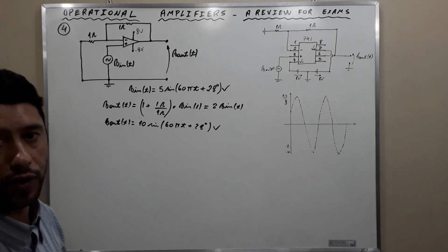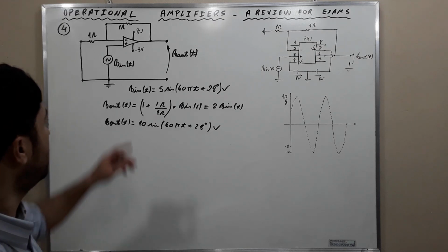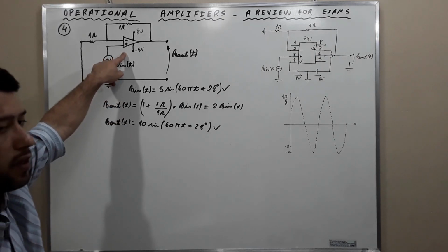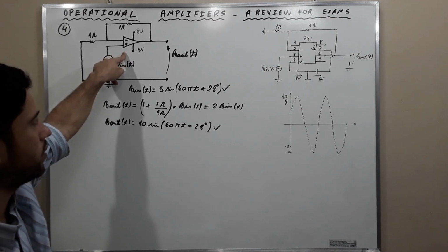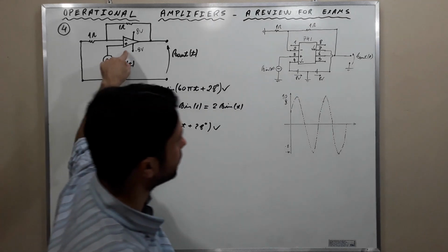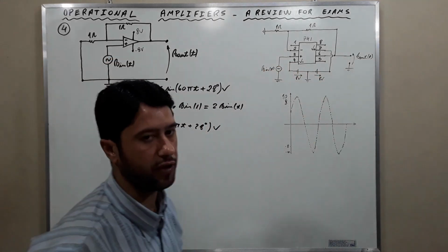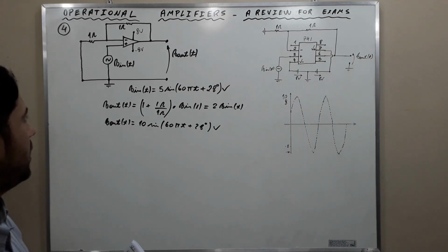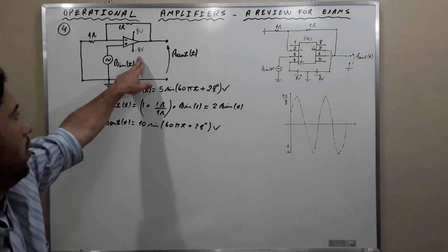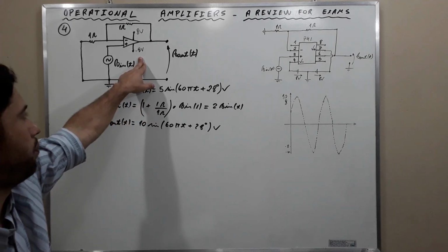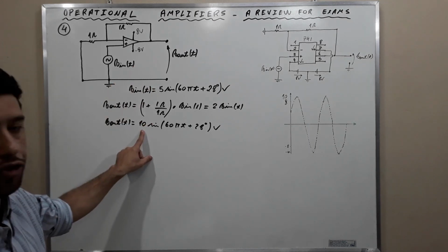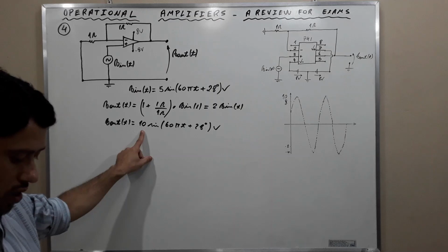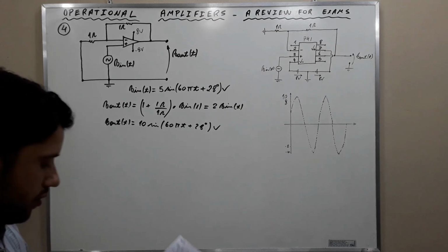The first thing that we notice is that we are limited by the external power supplies, okay, connected to pins 4 and 7, okay? Then, as our DC supplies provide only 8 volts, we are not going to reach 10, okay? We are going to stop at 8.